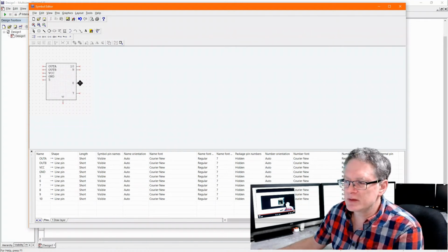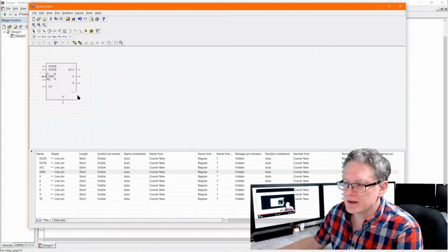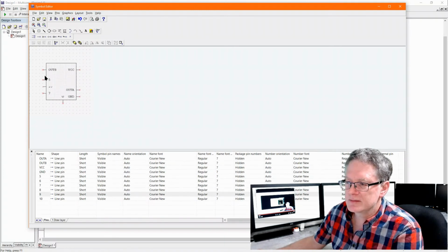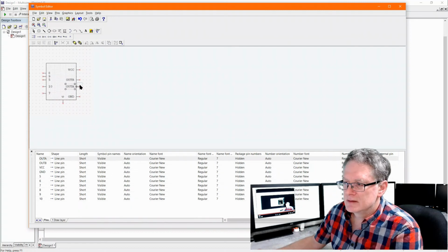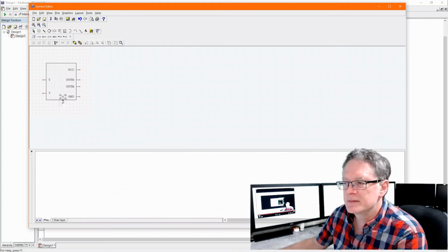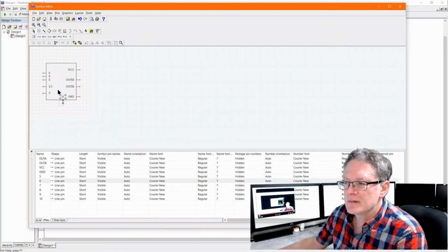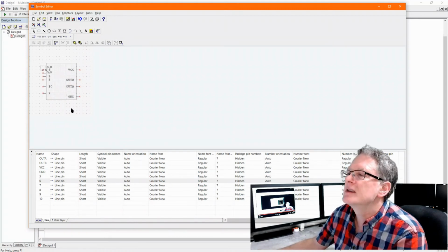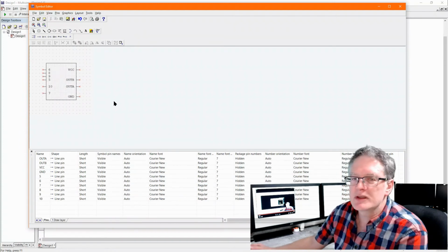It's an H-bridge driver, which usually has something like power and ground on one side. So usually we'd end up with VCC and ground on one side. And then the output to the motor driver, if it's a motor driver, you would have the outputs to that. So you hook this to power, hook this to ground, and then here's the hook to your motor. And then over here, usually in a schematic, you put inputs on the left-hand side, outputs on the right-hand side, and so the schematic would look something like that.